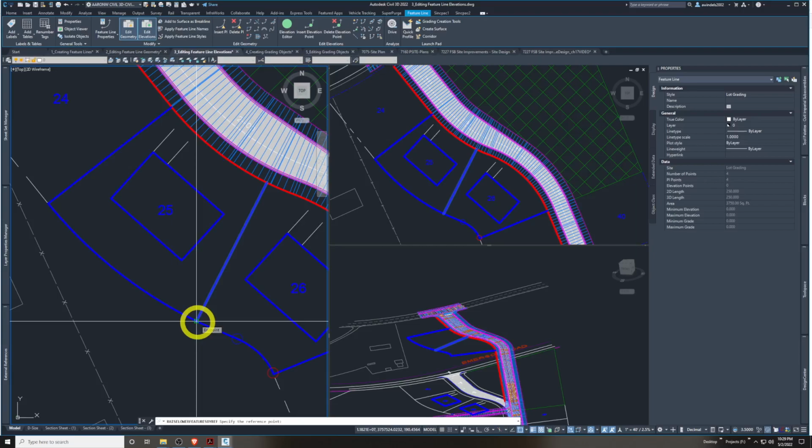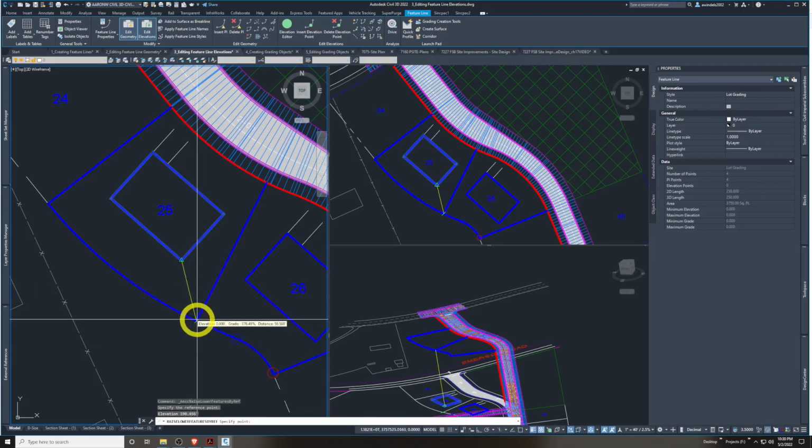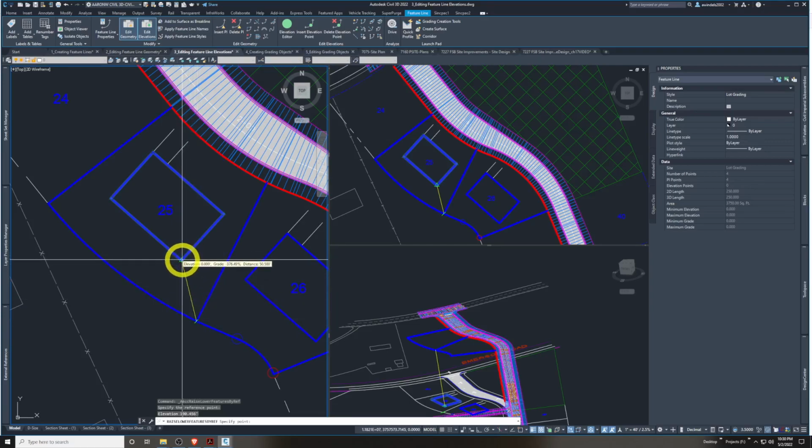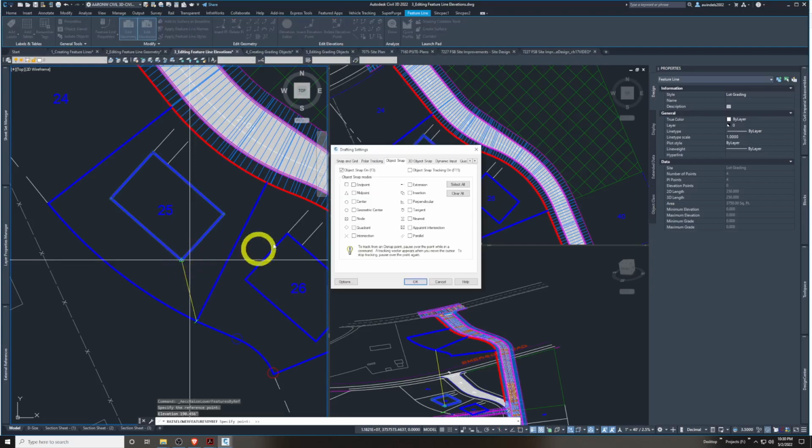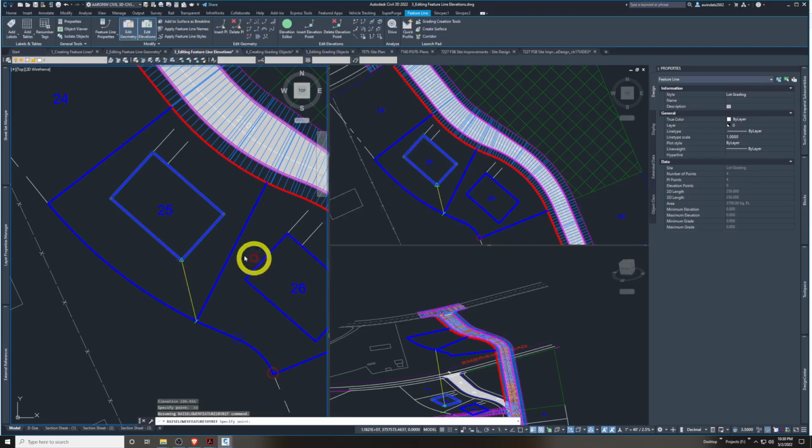Now, since I have that point selected, left click. It'll draw a temporary reference between the two of a grade, but I want to specify this point here. Let me turn on my endpoint snap again, or you can go to your OSnaps there. Make sure I go to this endpoint, pick that. Now specify a grade. We're going to type 2, and uphill 2% is basically what this means. Hit 2 there, okay? Hit enter.